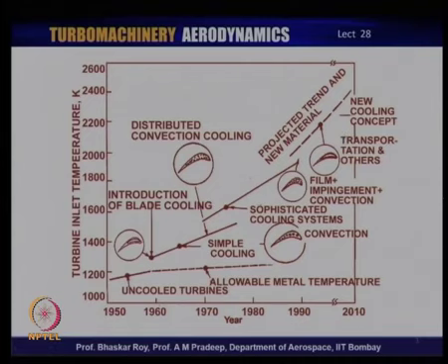And we shall see that since the pressure ratio has gone up, the efficiency of the turbine has been upgraded hugely through the upgradation of compression ratio, and this upgradation of turbine entry temperature coupled with the high compression ratio has given gas turbine engines a huge efficiency boost, and in terms of fuel saving, there is a huge fuel saving in the modern engines. So, turbine entry temperature boost is known from fundamental thermodynamics to give better and more efficient engines and provide more power.